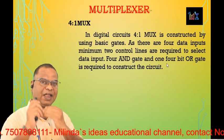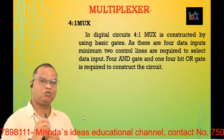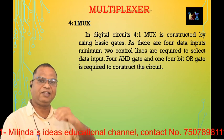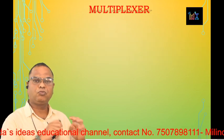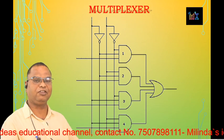The outputs of the 4 AND gates are connected to the OR gate, which gives a single output, and that is basically the output of the multiplexer. Now the logic diagram of the multiplexer is going to be displayed.